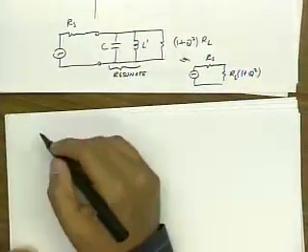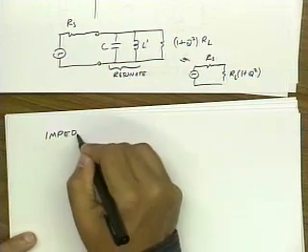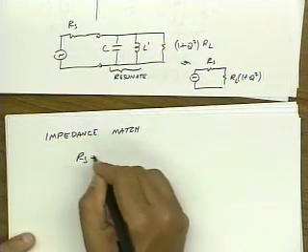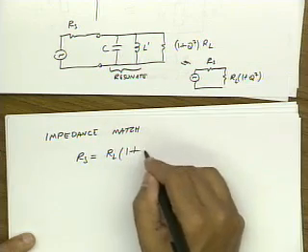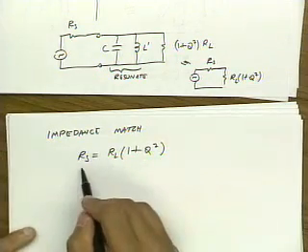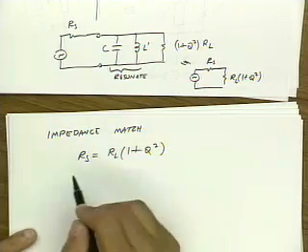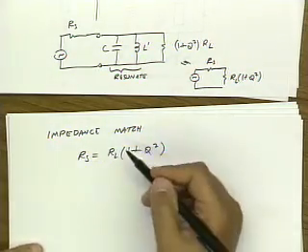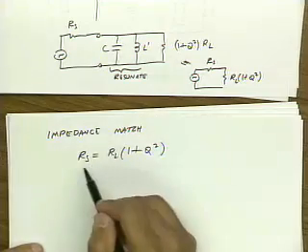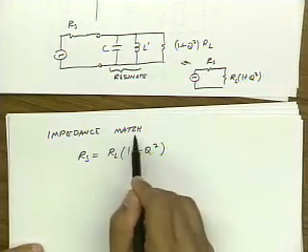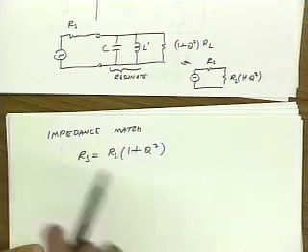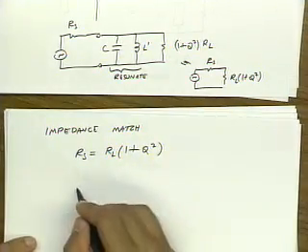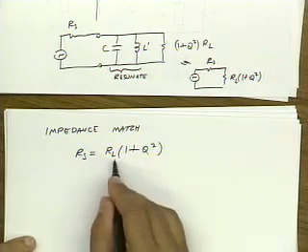So now if I want an impedance match, I would set RS equal to RL times 1 plus Q squared. Now this RS may equal the RS of the source, or it may be equal to basically the optimum source impedance or the optimum load, and so on and so forth. So it's not necessarily a match to the same impedance, it's a match to the impedance that you'd like to see. Okay? So if I solve this equation, remember RS and RL are usually given.